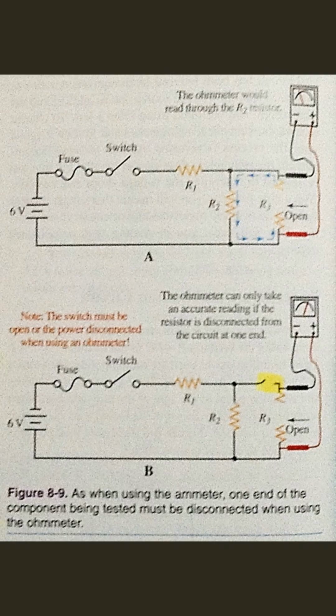A component connected in parallel with another component or device in a complex circuit design can be very difficult to detect on a printed circuit board. A false conclusion about the component being tested can be reached easily. A schematic of a complex combination circuit is essential in order to properly identify which components are connected in series or parallel with other components. Most electronic systems will have a schematic available. Good technicians use them as an integral part of the troubleshooting process.